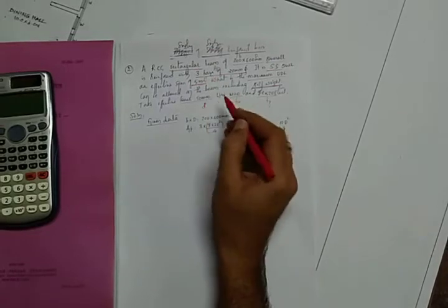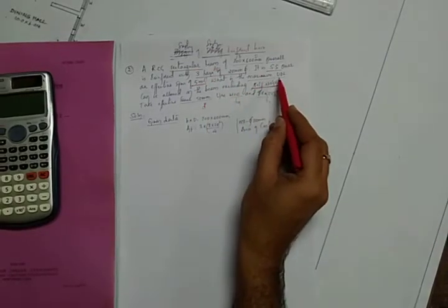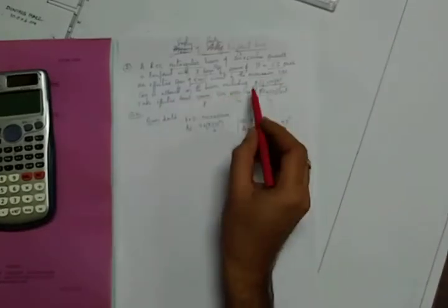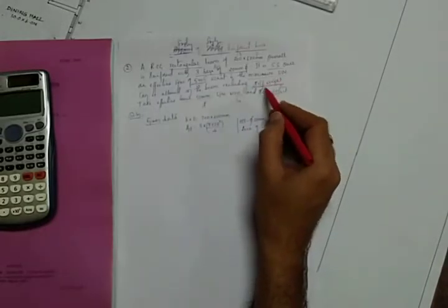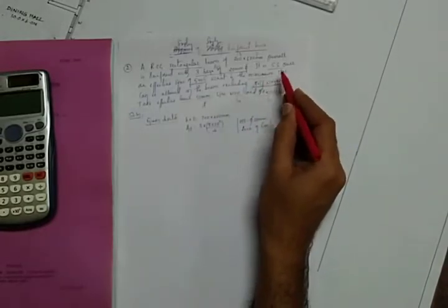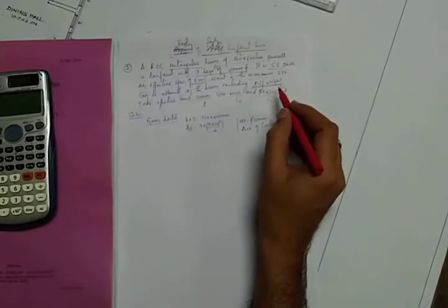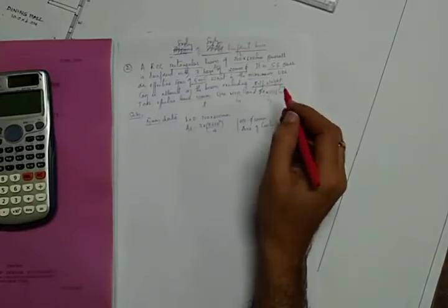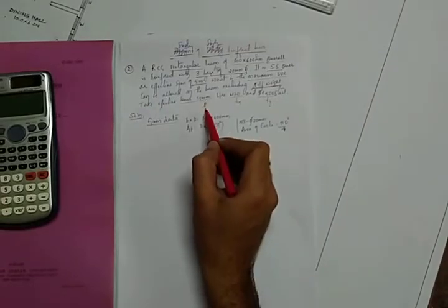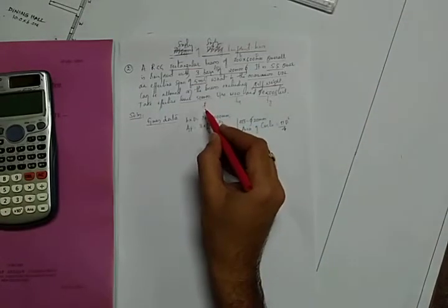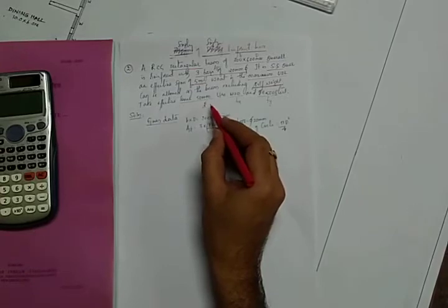So underline that. What is the maximum uniformly distributed load? That means UDL. Maximum UDL can be allowed on the beam excluding self weight, nothing but we have to deduct this self weight by calculating the total weight or total load that is coming on the structure. Take effective cover as 50 mm, d dash, otherwise we can assume. So this is an adoptable value.